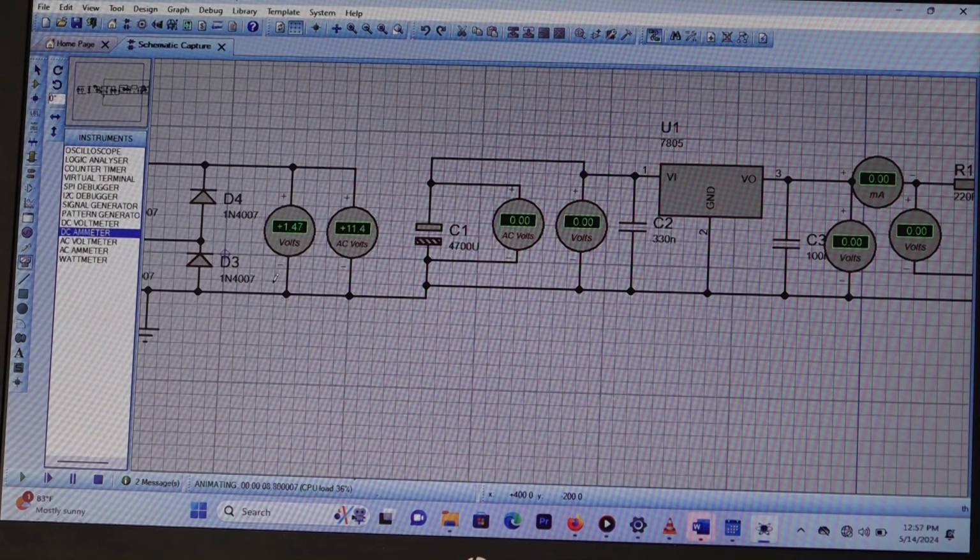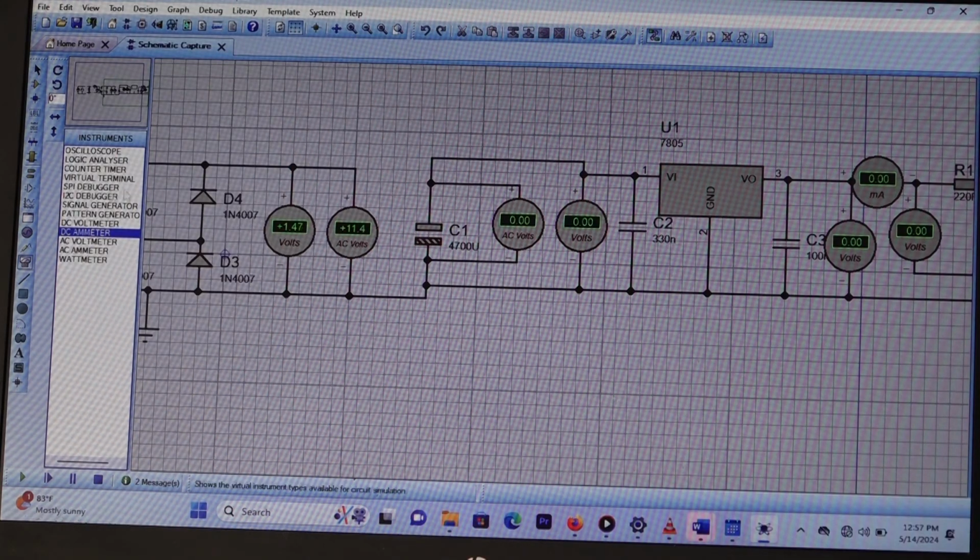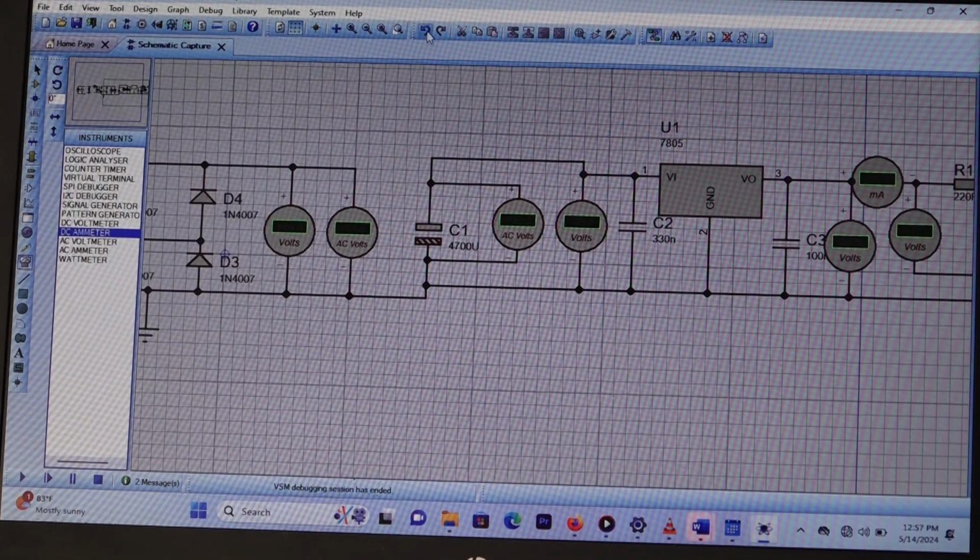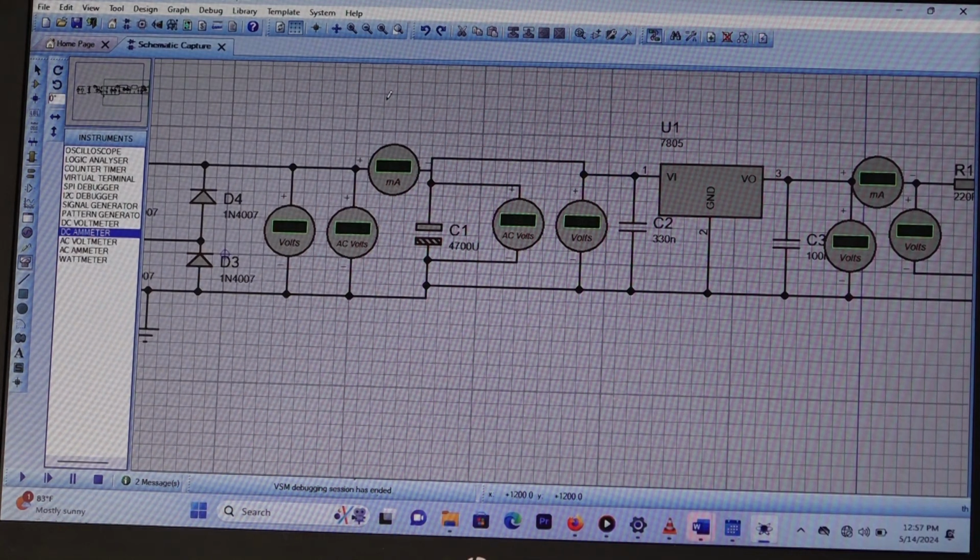So in case you have drawn the overall schematic circuit diagram, if you want to measure the input and output of each block, you just disconnect the circuit and deal with a small part. That's very important, and it's a trick of troubleshooting. Whenever you want to troubleshoot something, identify the problems and fix it, you have to go step by step. Okay? Is it clear?